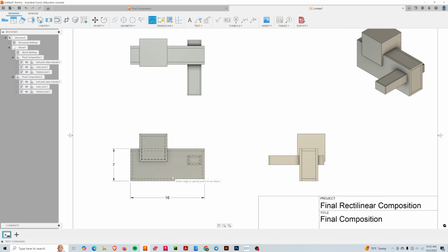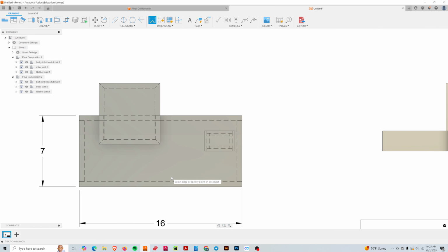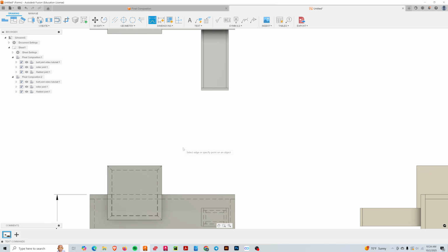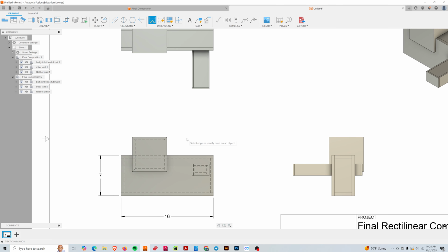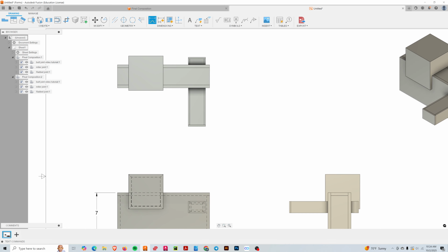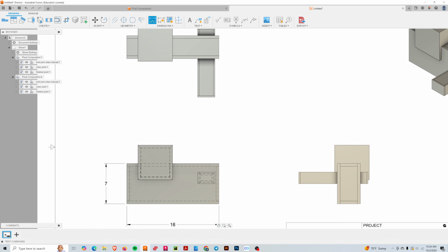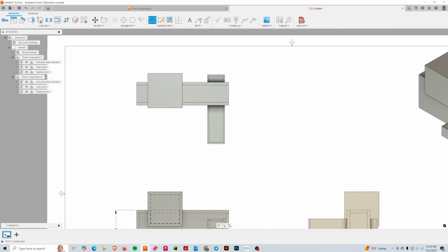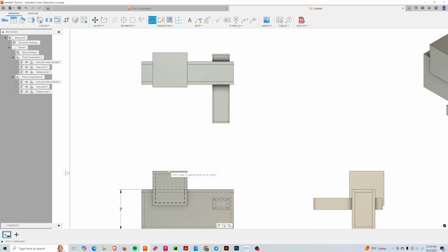But for this specific project, we are going to over dimension this just because it's easier. And what you want to do is make sure you have the size of everything wherever it's clearest, right? So, for example, this I know is a 6x6 inch miter box. I can put the measurement here and here or here. Actually, we need all three sides.